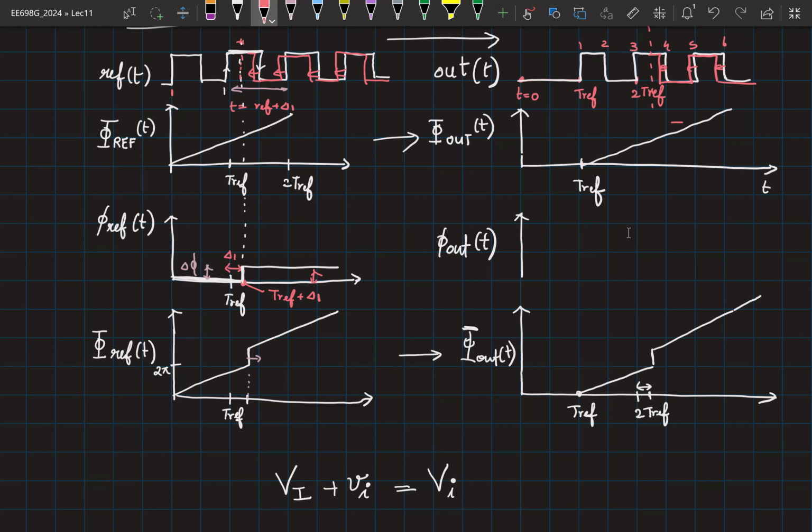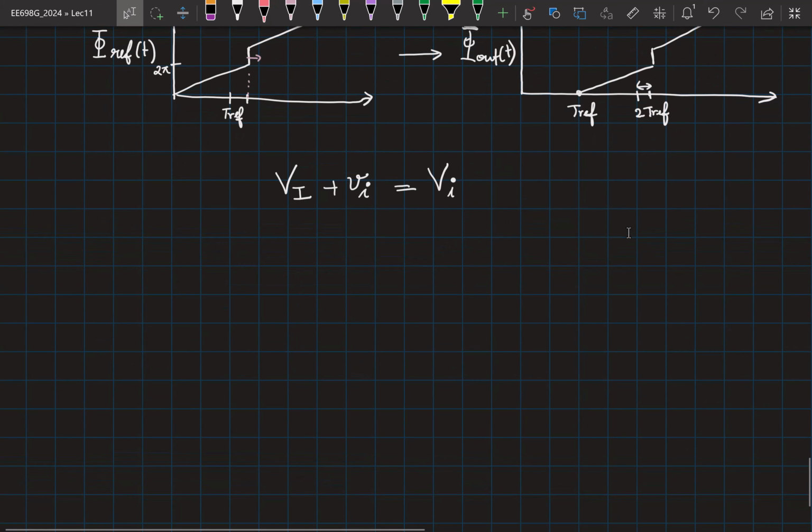If the delta phi is larger, then instead of a falling edge, you will encounter a rising edge immediately there, to be at the position of the falling edge. Instead of a falling edge, you will get a rising edge. So again, you are talking about certain corner cases, right? One, the assumption is these are small signals, meaning the phase difference is very small.